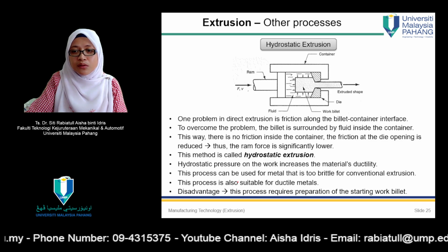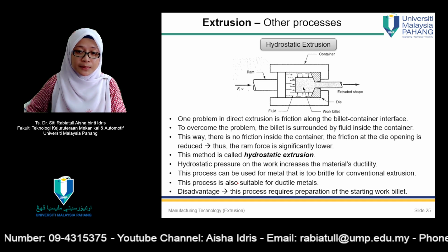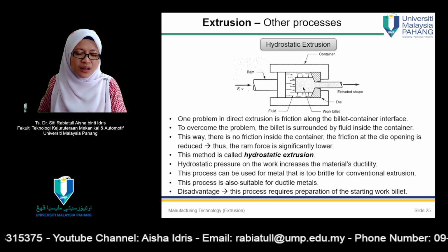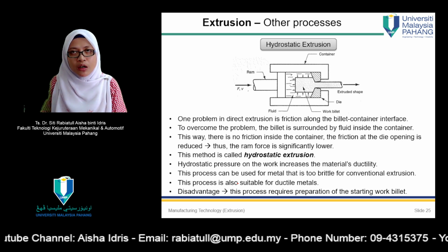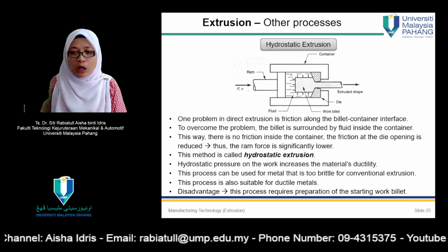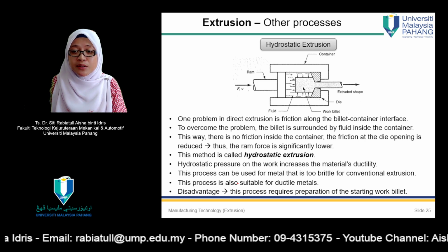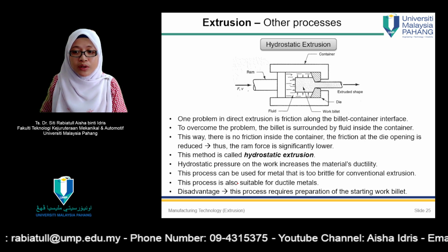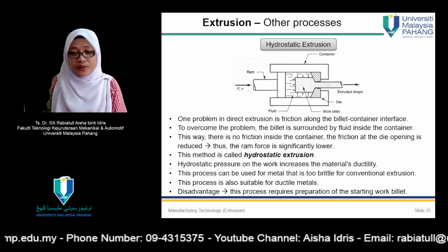Other than that, there's also hydrostatic extrusion available in the market. The process is more or less the same as direct extrusion. However, in this case a fluid is used to give pressure to the work billet, and therefore no friction is involved in this process.